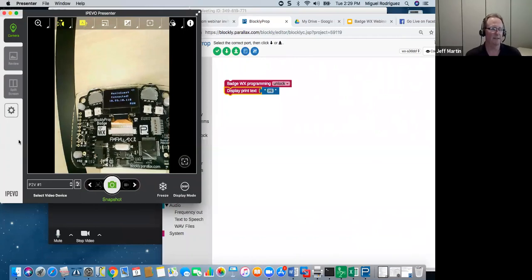And then another option is to put a small text file on an SD card and stick it in the SD slot before you power it up. And this is described in the product documentation too. If that Wi-Fi text file contains just 2 lines, where the top line is the name of the access point and the bottom line is the passphrase, upon power up, the badge will load that file and use those credentials to try to associate with that access point. That's really handy for cases where the passphrase is kind of long and difficult to type in manually.